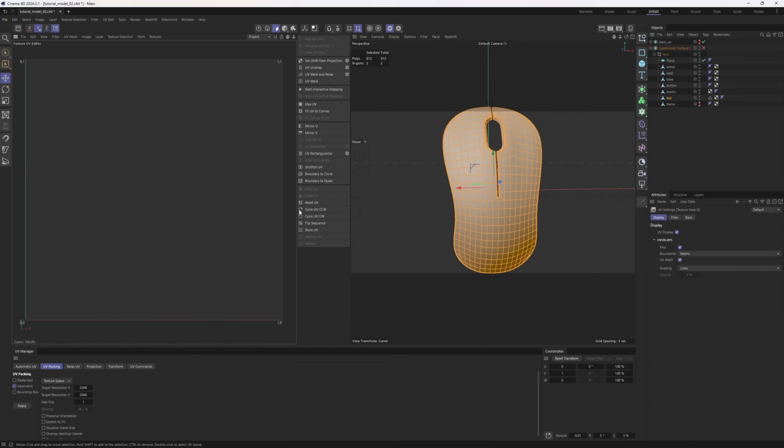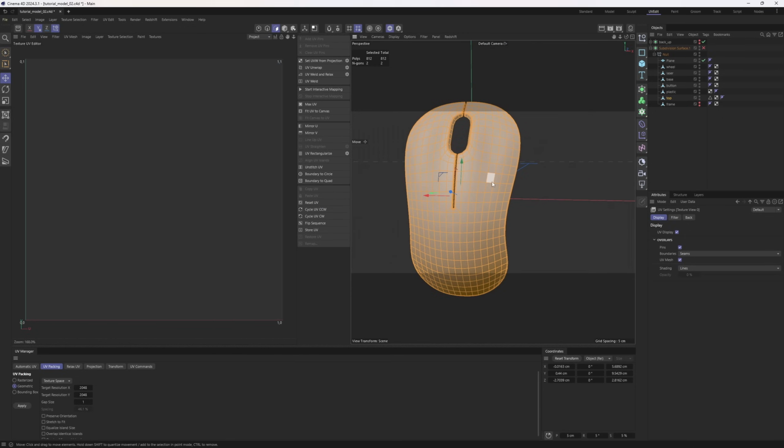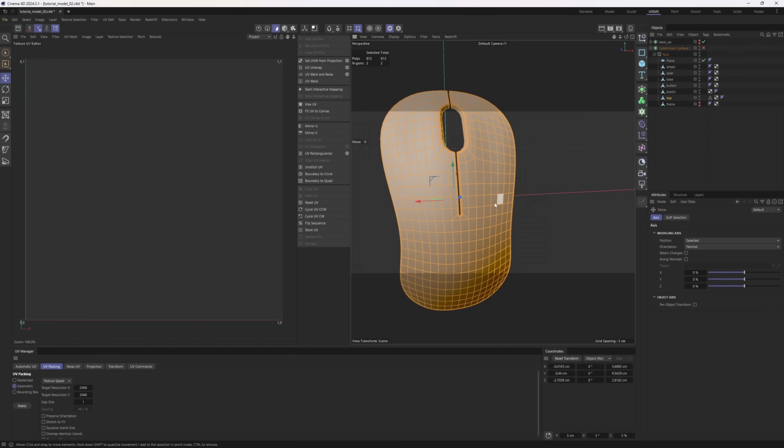First, let's turn this off and reset the UVs. By the way, before recording this part, I reset the UVs of these objects. So that's why you don't see anything on the left side. You can do the same. You will probably have broken UV. So just select all the polygons and click on reset UV for a fresh start. Again, we could use